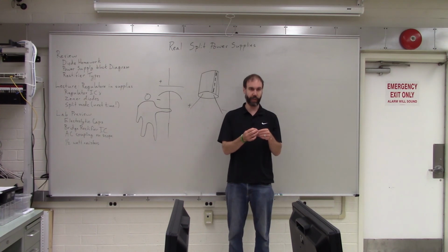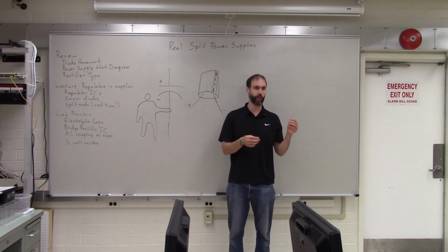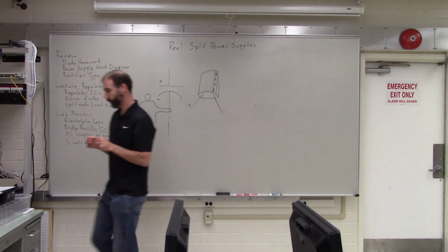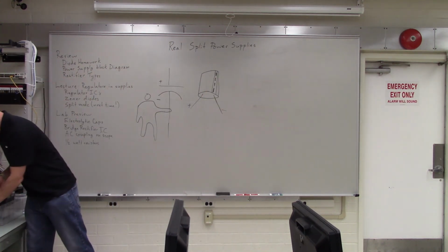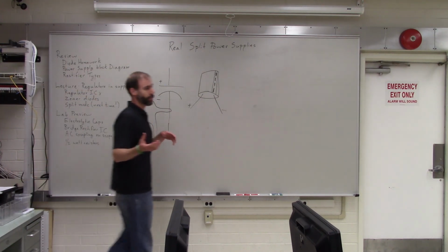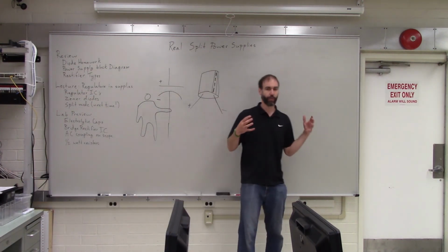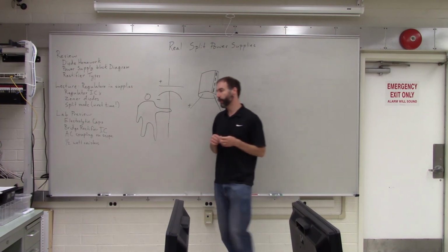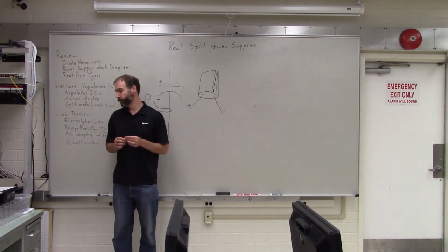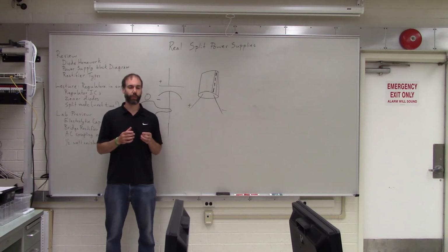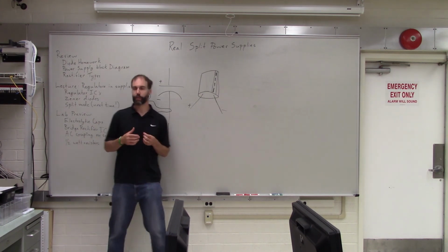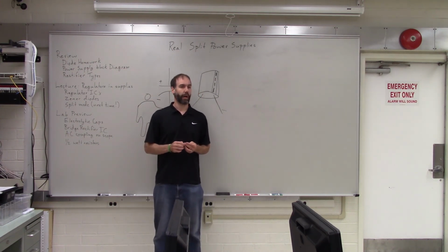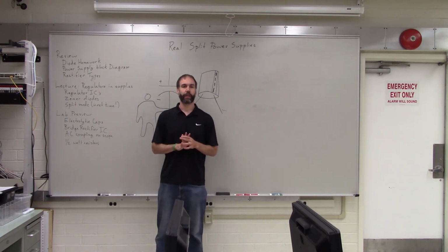Be sure you use the bigger ones. If it looks like just a normal 1 kilo ohm resistor, that's not right. Make sure you get a bigger one. The bigger ones can withstand more current. They have more room to dissipate the heat, and so they can take the amount of current that we're going to be providing tonight. If you just get the normal small ones, they can burn up. So make sure you use the big half-watt resistors. Any questions about that?